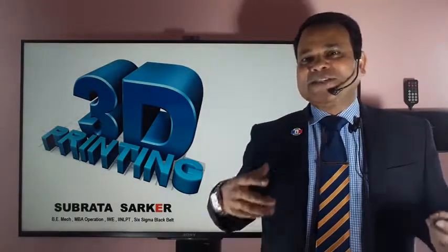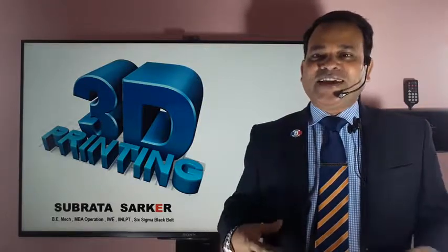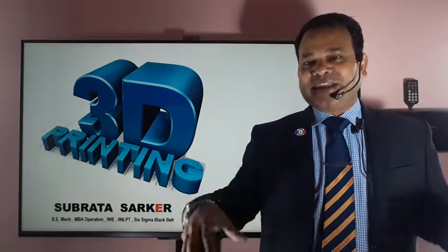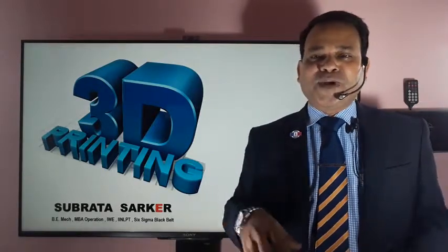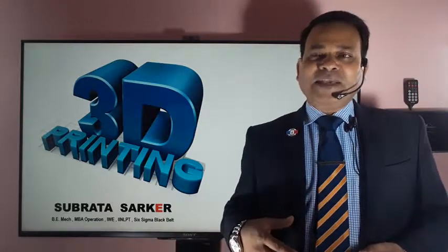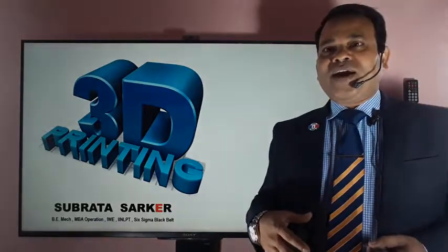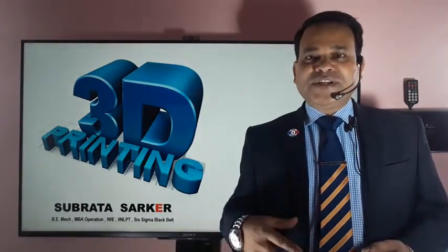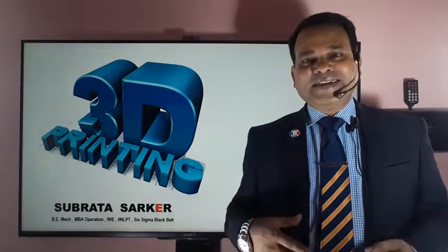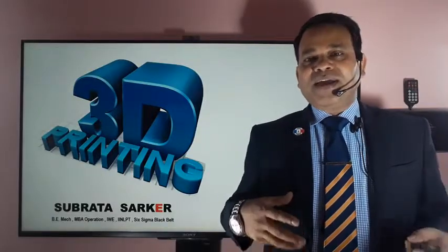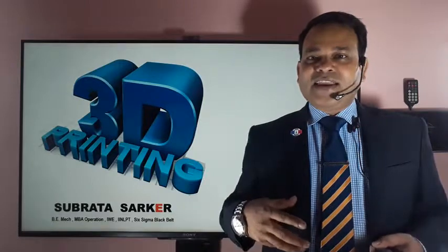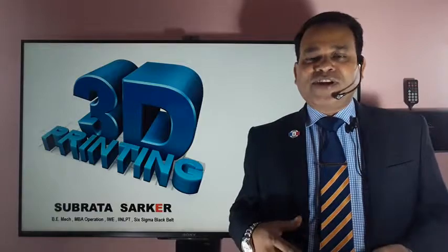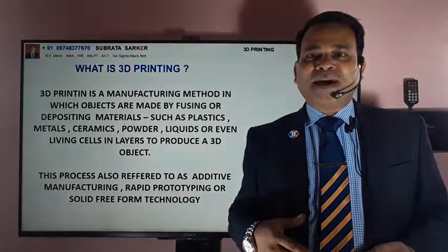Today, I'll be discussing a special manufacturing technology, that is 3D printing. 3D printing is not a technology for printing on paper and documents. 3D printing is basically a manufacturing method where objects are made by either fusing or depositing material like plastics, metal, ceramic, liquid, even living cells, layer by layer to create 3D objects. This is also called rapid prototyping or additive manufacturing.